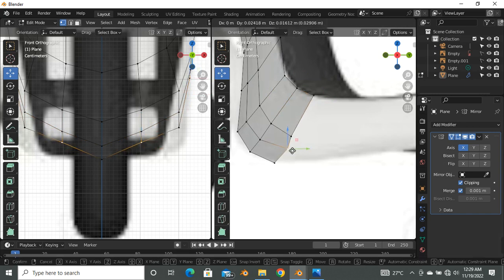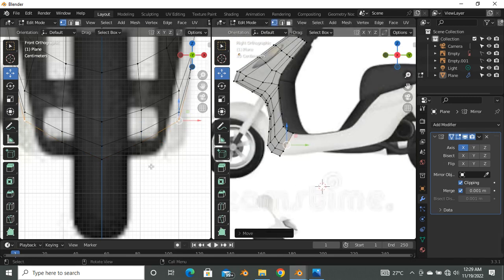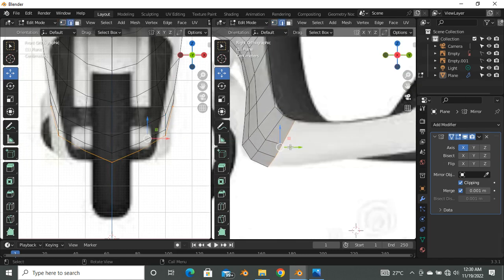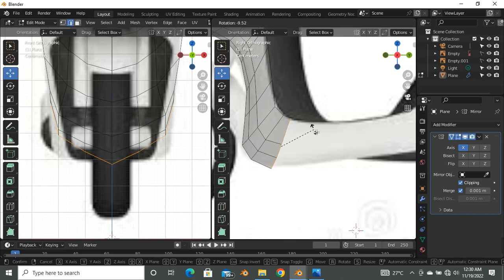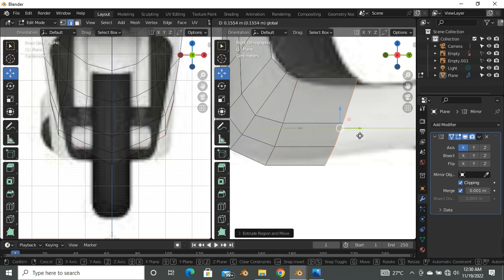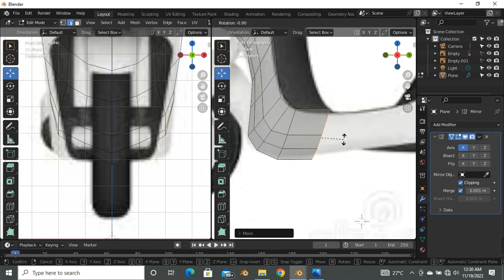Then I'll adjust this point to this point, following my reference. So just try to move some vertices and ensure it's simple. And I'll hold Alt again, select this, say 2 for edge selection. I can rotate this also to this point. I can say E to extrude that, right click to release and push, and I'll say R to rotate, and I can push this upwards.